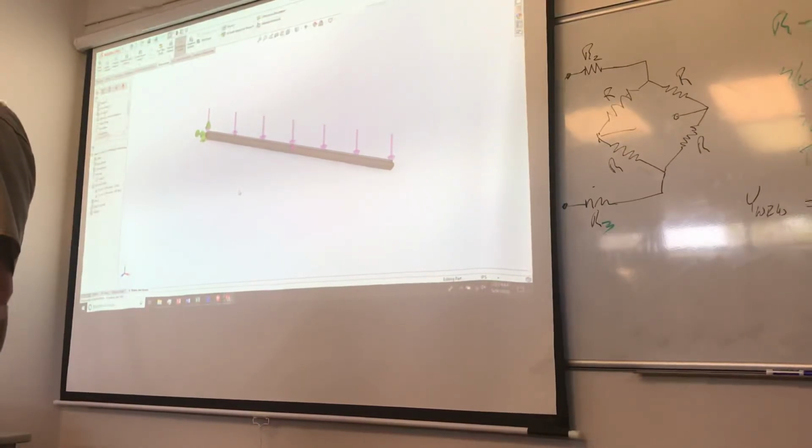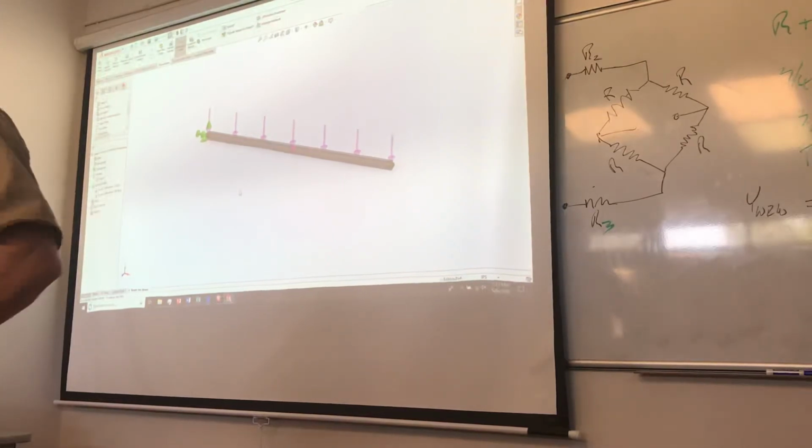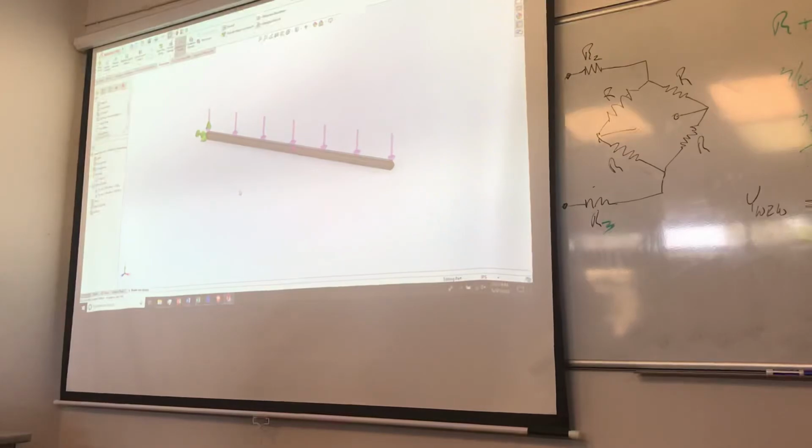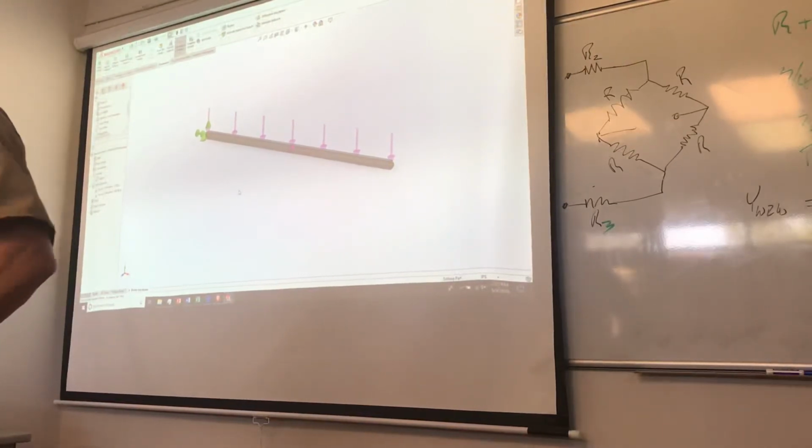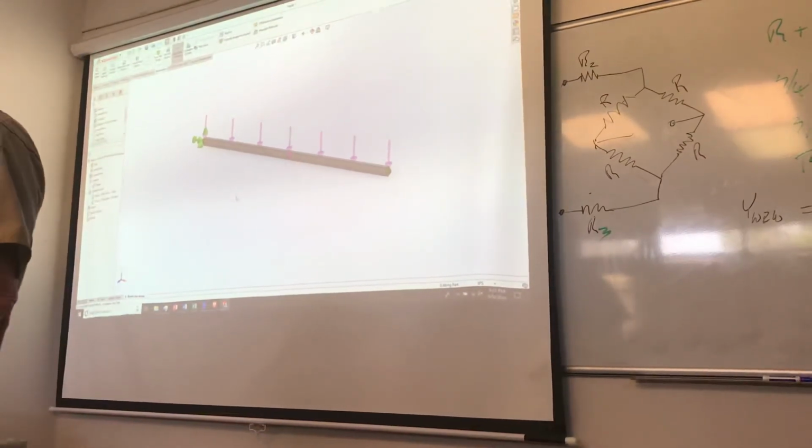I like this. Good. What's the tricky part about this whole thing? Where to put the darn stuff, and how to put it, right? That's the hardest part: what to save it as and where to put it. All the profiles have to be saved as a library feature part, and you have to get out of them before SolidWorks will let you copy them around. You have to create them someplace and then exit them out of SolidWorks before it's happy with letting you move them around.